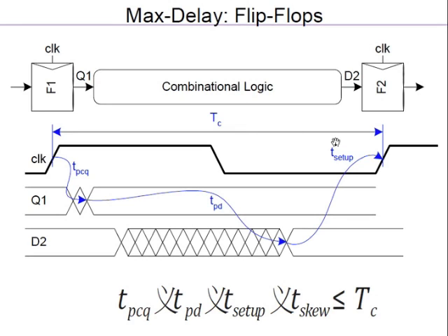Which means the clock period with which you are running the chip, as you reduce the supply voltage, should also be adjusted accordingly. If you keep the same fixed clock period which you use for a higher voltage and you make the chip run at a lower voltage, it will fail because the timing will be violated, right? So for every clock period there is a minimum voltage at which it will run properly. Below that voltage the chip will fail because it will violate the timing margin. Above that voltage should be okay. It will just come fast, and everything will come and settle.